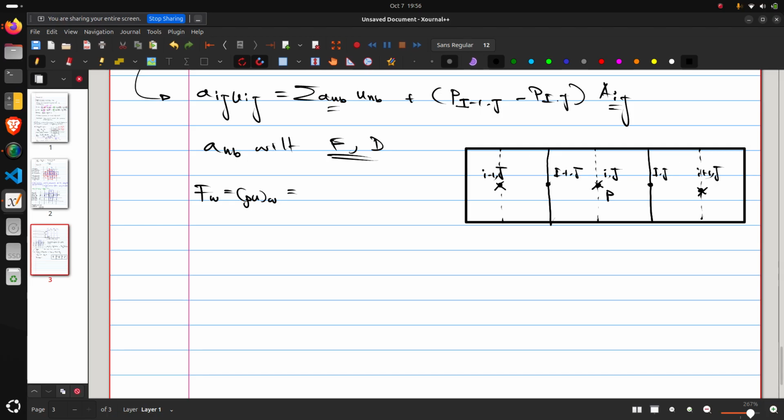So in this case, where we are considering the point P, which is the cell center for the x direction staggered grid, we see that the west face is this one, right? So if you need the flux from this part, we can just take an arithmetic average of the fluxes at these 2 points, because we have the u values here. We do not have the u values in the original grid cell center, because we are only storing it in the staggered grid cell centers.